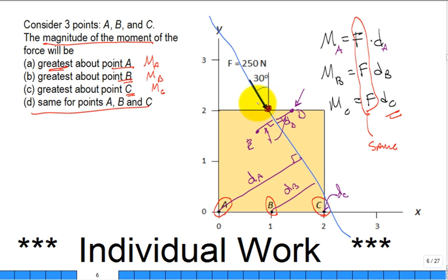So that force around point D will make it want to rotate in what direction? How would I describe that direction? Counterclockwise. And around point E, it would want to make the object rotate clockwise. And now we've got to pick a positive and a negative sense of direction. All right. Which one did the book? Maybe you read the book, right? Which one did the book say, look, for the whole book, let's just pick this one as being our positive sense of rotation for our object?